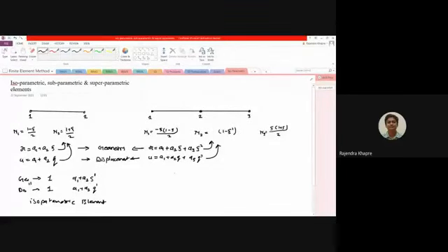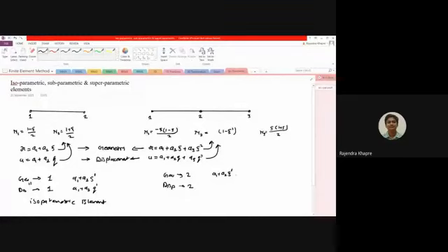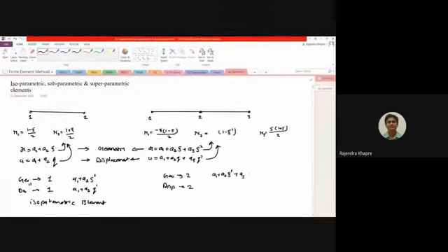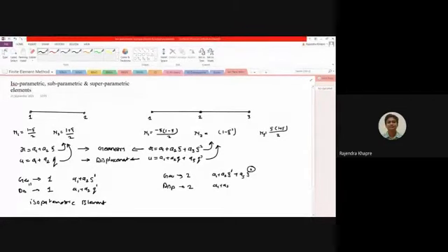Okay, if you consider the three noded bar element. Okay, so in the three noded bar element, geometry and displacement. Now here if you see the order of the polynomial which is used to define the geometry, so to define the geometry what did we use? We have used a1 plus a2 times xi to the power 1, okay, plus a3 times xi to the power 2. So the order over here is 2. Similarly, if you see the deformation polynomial, this is a1 plus a2 times q plus a3 times q to the power 2.